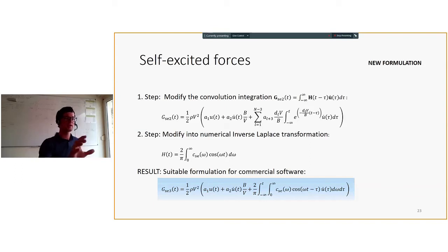So this has been done, and this self-excited force model 3 shows that we have reformulated the rational functions, and this kind of format is now a candidate which could be implemented in the software. We already have access to the hydrodynamic interface that has the same functionality, plus we have some quasi-static contribution that we also have to take care of inside the software.